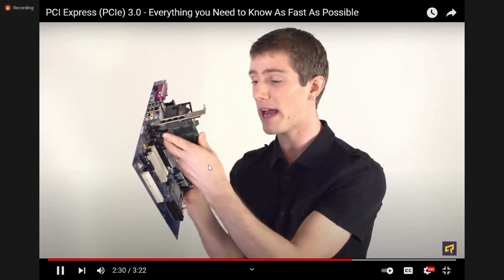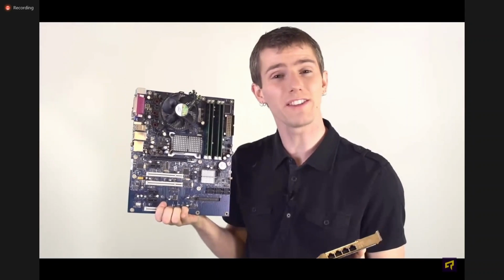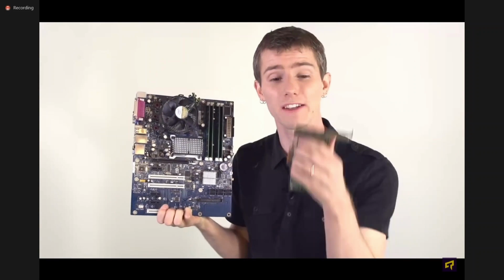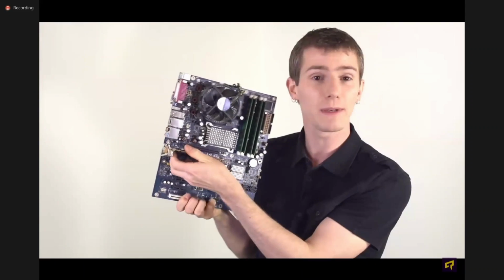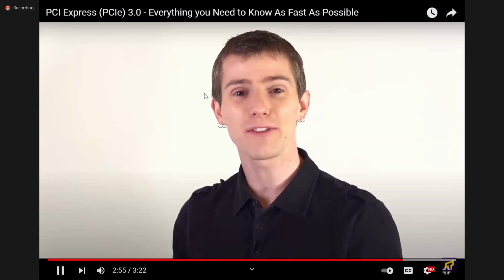Gigabytes per second of bandwidth in order to operate at peak efficiency. That means if I have an older PCIe Gen 1 motherboard, I'll need at least a 4x slot or a hypothetical 2x slot to get the bandwidth I need because it's only 250 megabytes per second in a 1x slot. However, if I have a PCI Express Gen 2 motherboard, I could even use a 1x slot to get everything I need because that'll be about 500 megabytes per second. Thanks for checking out this episode of Fast.